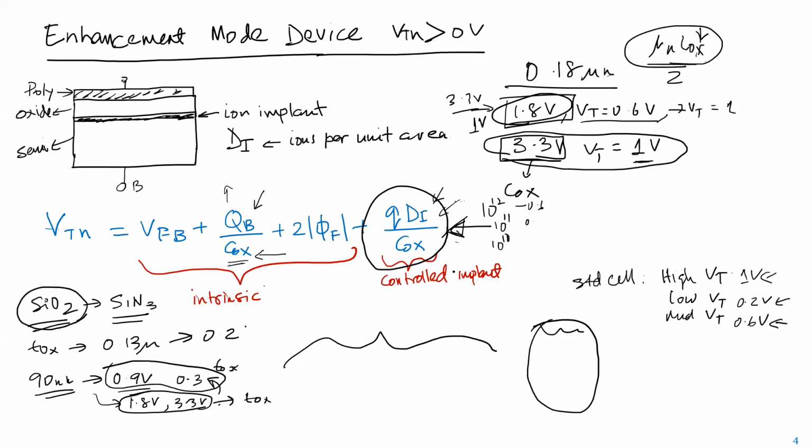So with that one, you're keeping your VDD, the type of your device, fixed. In 28 nanometer, it will be whatever, 0.3 volt or 0.5 volt. In 40 nanometer, it's 1 volt. But your VT will change with just this implant. In that 28 nanometer, you probably have a 1.8 volt device too, but with a higher VT. But for that one, the TOX will change. They will make it higher.